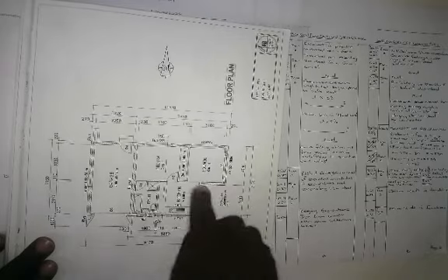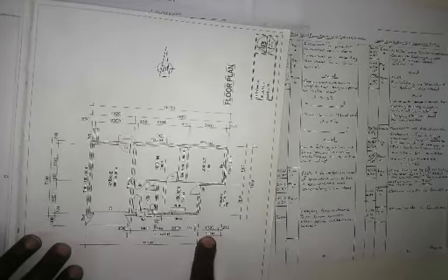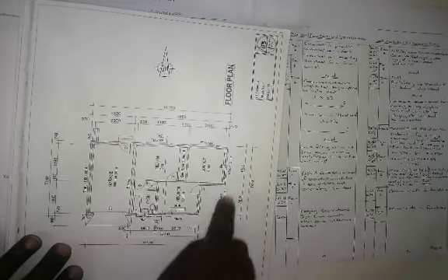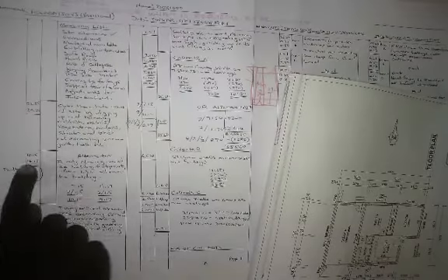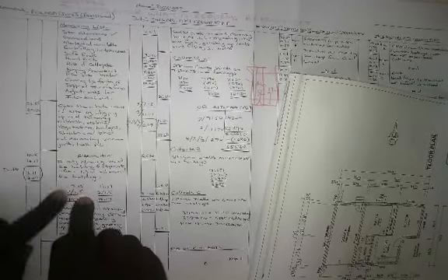But remember, on this one, you've got some sort of recess here. So you will need to deduct this area over here, because when you said length times breadth, you also covered this whole section. We don't do over measurements in quantity surveying. You need to deduct this area, 3.11 by 2 meters, because it's not part of the footprint of the house, guys. So that's how it plays out in terms of the dimensions.